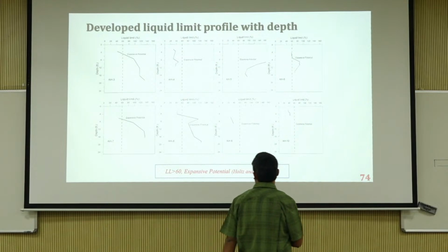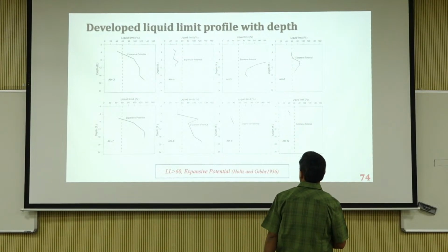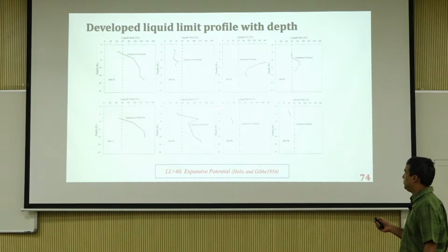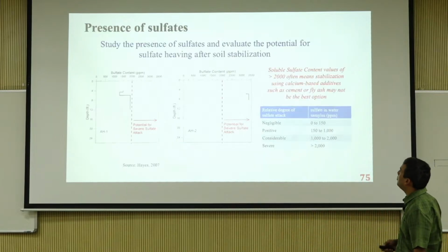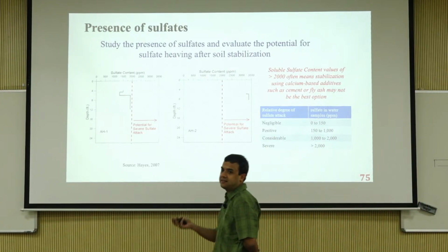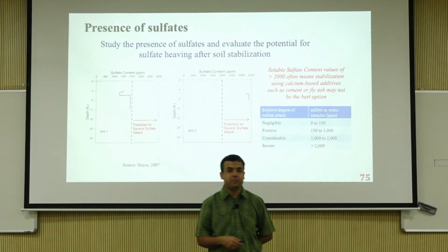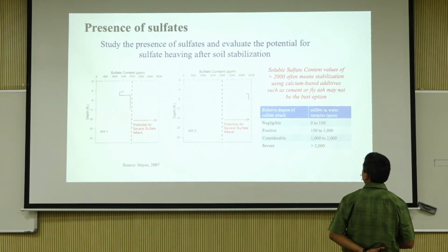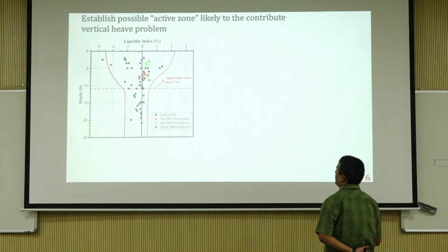And then we characterized the first 10 boreholes, then we had 2 more boreholes. We did soluble sulfate content, because if there is sulfate, you cannot do calcium based stabilization. So that's one thing. But this is the most important question.